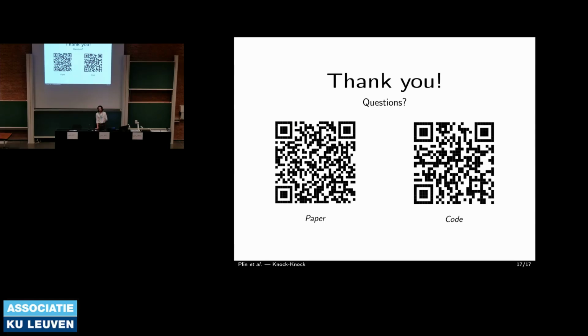Thanks for the talk. One question, so you mentioned nonlinear functions. So we know that for caches, nonlinear functions appear when you have a non-power-of-2 number of cache slices. Is there a system where it is already known that you have DRAM addressing functions that are not linear? Yes, for example, on some AMD processors, the slices of physical addresses that are mapped to the DRAM are not continuous.